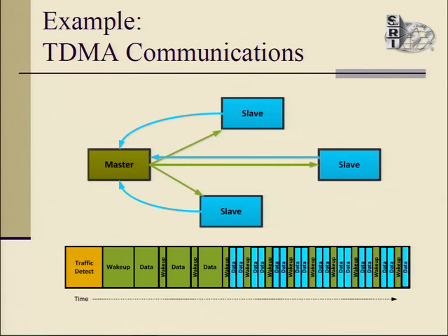They're executing a low duty cycle protocol to preserve their battery life. And so in this communication process, the master initiates by sending a long signal that the slave devices detect on their duty cycle wake up, and then they respond with data. This network is completely uncoordinated, so we don't know what devices are out there. There may be thousands of devices possible, and a dozen that we can see at one time.